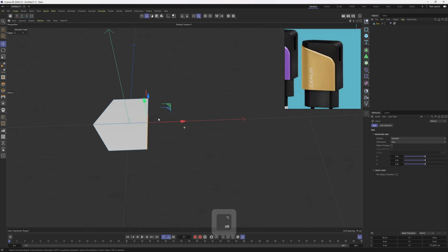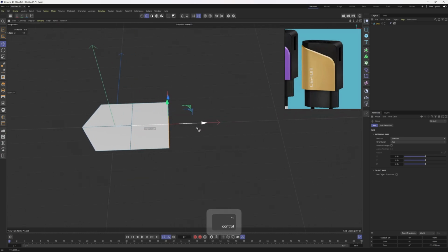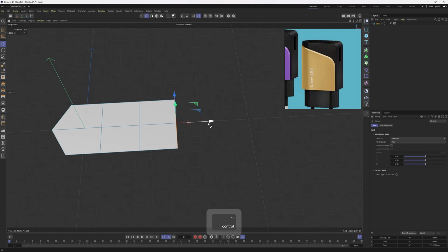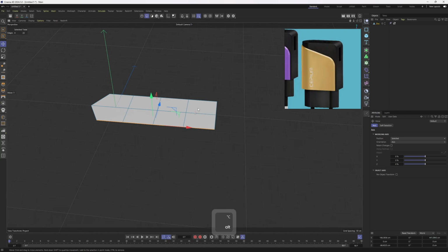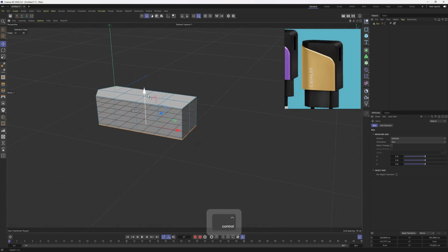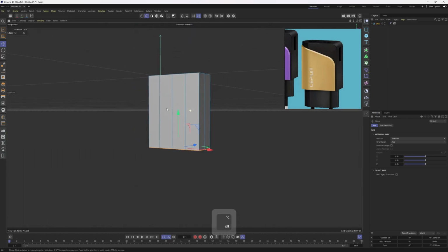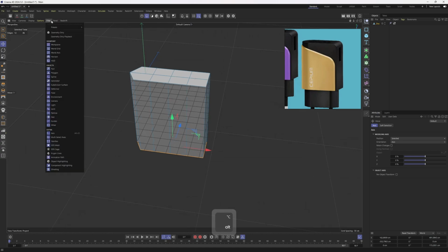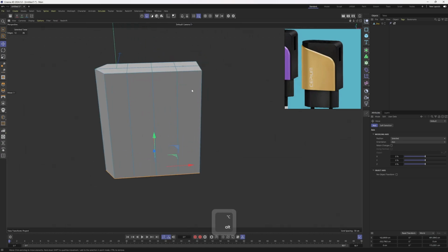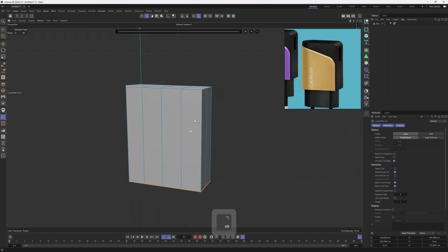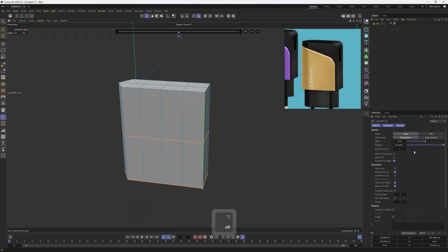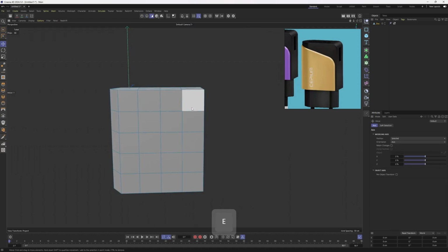Okay, now let's select these edges, hold down Ctrl and extrude these, let's say 3 times. All right, now let's select these boundary edges by holding Shift. Then I will hold down Ctrl and bring these down. Let's see. Yeah, we need something like that. By the way, let me turn off that work plane. Now I will hold down Shift and add that loop cuts in and increase up the cuts to, let's say, 4 because I want a uniform mesh.